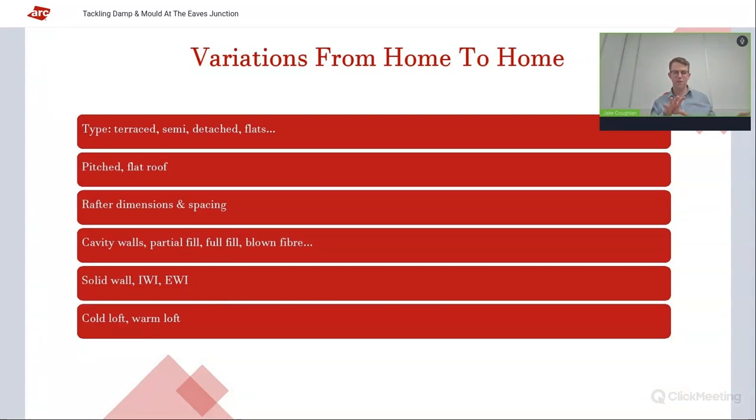That means that you've still got your exposed eaves detail. So even with the warm loft, this product can be installed. I recently went to a property a few weeks ago, which had exactly that situation. It had plasterboard put up and round, which is inadvisable because it wasn't insulated, but then the eaves were still exposed, creating a huge thermal bridge there.